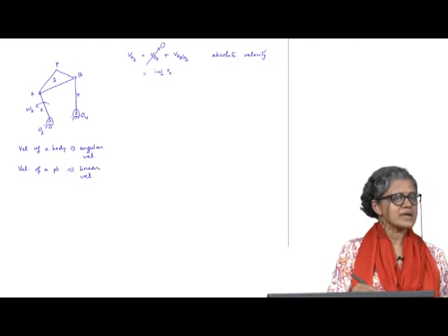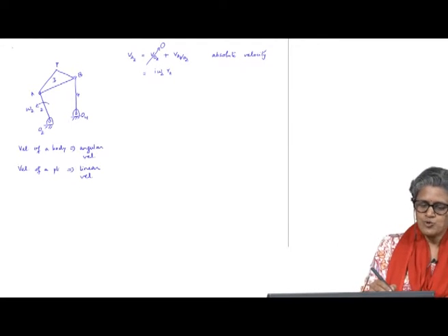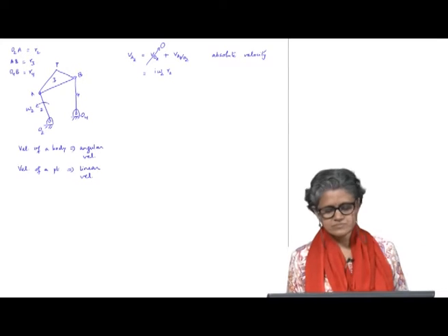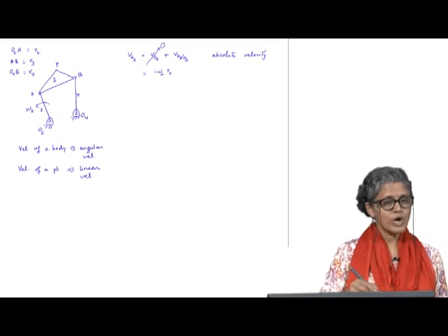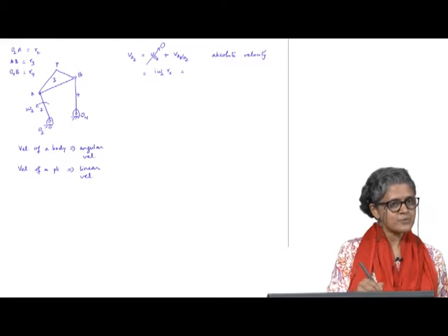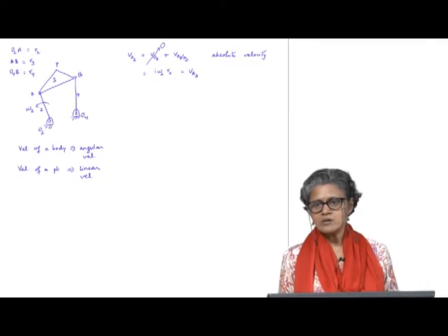R2 is my length of link 2. So, here I have O2A, length R2, AB equal to R3 and O4B equal to R4. Now, if I look at body 3, the velocity of A on body 2, because A is common to body 2 and body 3, is also the absolute velocity of A on body 3.